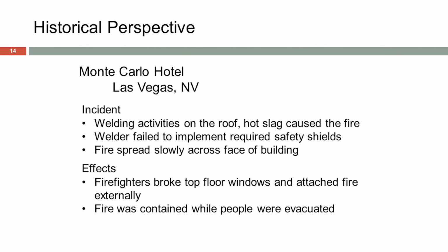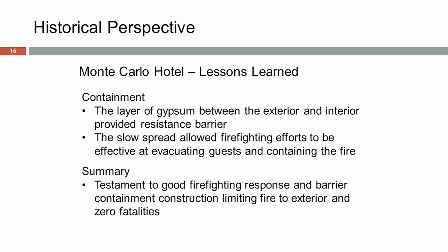So we're in later developments of systems and buildings, and there's more compartmentation in design concepts. And in this case, there was a gypsum layer providing isolation from the exterior to the interior that helped keep the fire under control and kept it outside of the occupied environment. As a matter of fact, the firefighters didn't fight from outside. They actually went into the upper floors, busted out windows, and they were able to get their fire hoses by hanging out the windows and put the fire out.